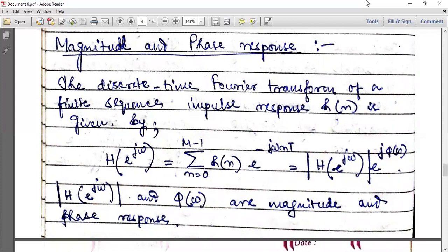How it is related to the difference equation. Now, I will be relating the hardware elements with the difference equation that I've written in my note. You see, the memory element is where the past inputs x of nT minus mT and past outputs y of nT minus kT, as well as the constants a_m and b_k, can be stored. So for this, the memory element is required.